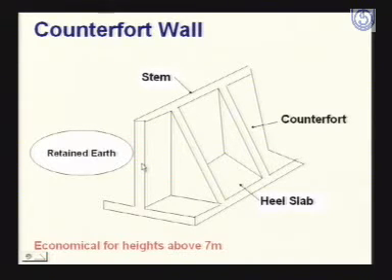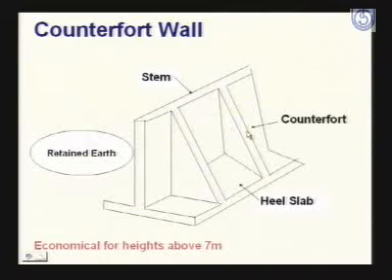To reduce the size of these different structural elements of this wall, we aim at the reduction of the bending moment. And to reduce the bending moment, these counterforts are used in a counterfort wall, and these counterforts are provided at an interval of about 1/3 to 1/2 of the height of the wall.